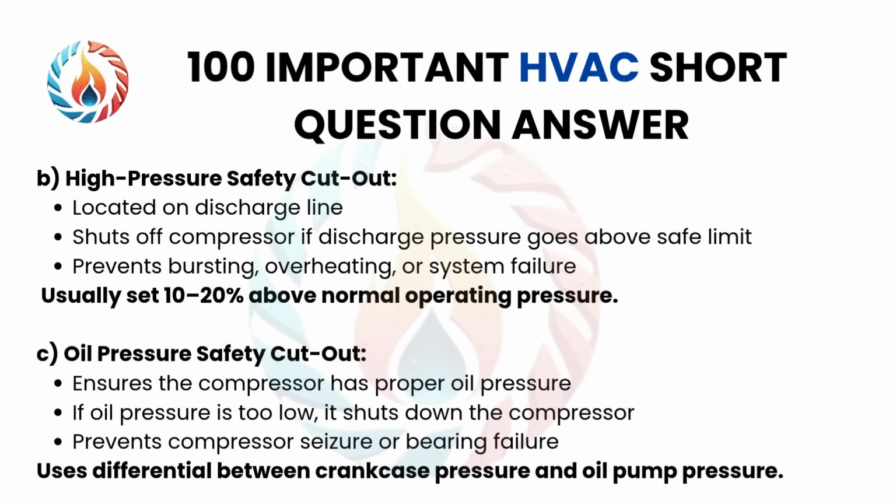C. Oil pressure safety cutout. Ensures the compressor has proper oil pressure. If oil pressure is too low, it shuts down the compressor, prevents compressor seizure or bearing failure, uses differential between crankcase pressure and oil pump pressure.